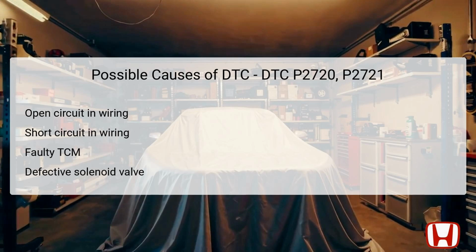If the other components check out, the solenoid valve may be defective, which can manifest as inability to either engage or disengage the lockup clutch as required. Understanding these possible causes guides the technician in conducting thorough inspections to pinpoint the exact issue. It is essential to carefully trace the wiring and harness for any visible damages or breaks, and test each component as outlined in the diagnostic procedure.